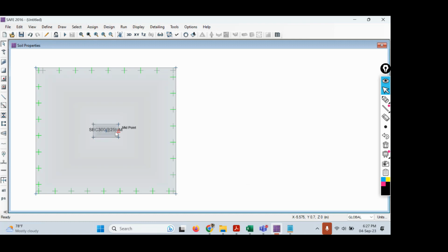So once we finalize the area of the footing and depth of the footing, then only we'll go for the drawing of the stiff area or design modeling of the stiff area. So that is punching shear area, that is punching shear should be safe. Punching shear is nothing but two-way shear. So once punching shear is safe, then only we'll go for the stiff portion design.